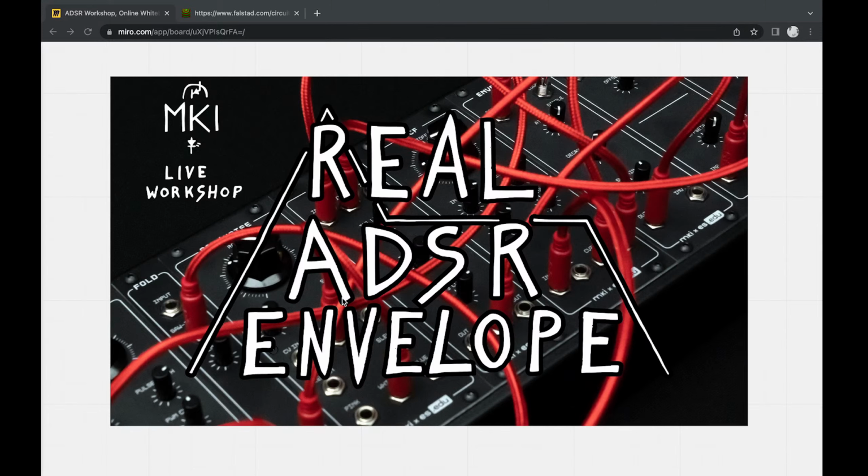If we talk about envelope generators first, without the specification, we can basically say that an envelope is a device that receives a trigger or a gate, for example, from a keyboard or from a sequencer. And then in response to that gate or trigger signal, it outputs a rising and then falling voltage.